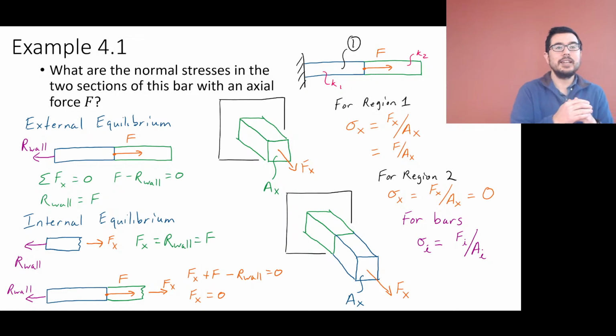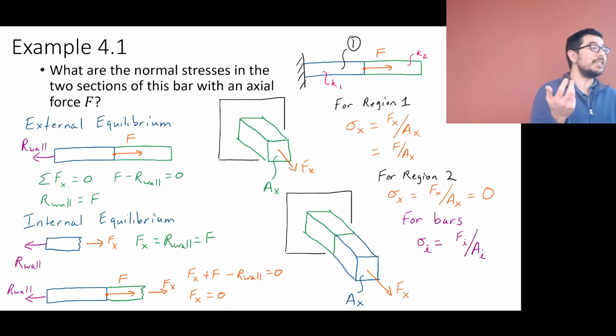Do you think that calculating the internal force will be the hard part of the problem or the easy part when you're trying to calculate normal stresses? Calculating what that internal force is typically going to be the harder part. In bars, you maybe have to do equilibrium on a whole truss system to figure out what the internal force is, and then it's like, okay, that's normal stress. Boom, that's right. So being able to handle the equilibrium portion of these problems is extremely important.